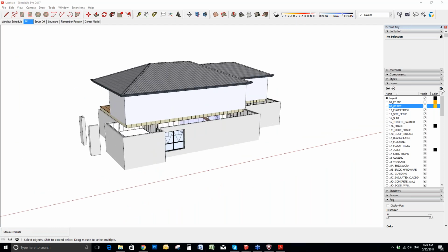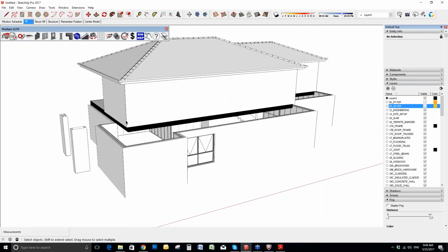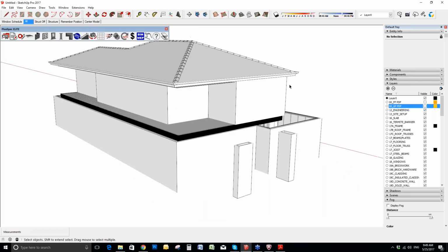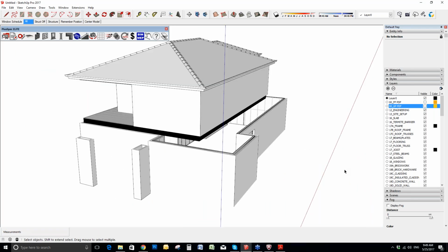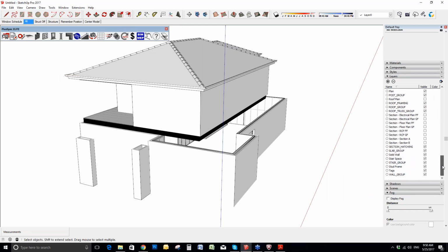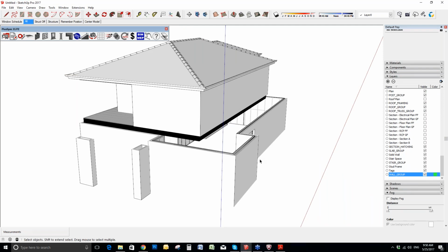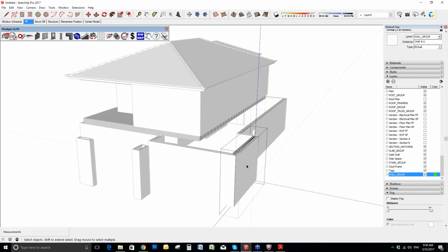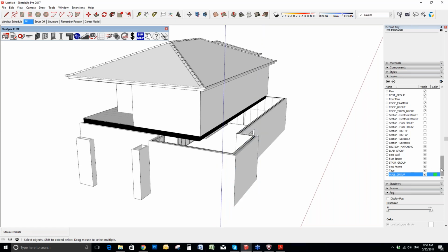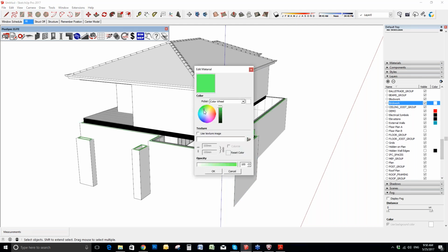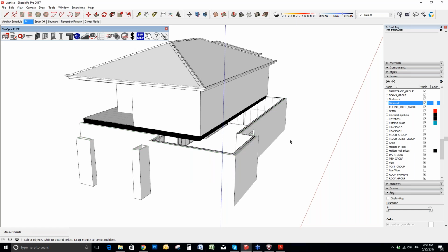If I do that by clicking on this here, color by layer, you can see that you can change the layering systems. So for example, the wall tool, if I go down and assign a layer to those ones, by the wall group, I'm going to click on that and turn it to be green. You have to know what layers you want to show too. So probably do it on the brickwork layer. That gives you the ability to divide your project in different ways, or to display it in different ways, right? So it can read differently, but I don't necessarily think that it would help you estimate better.